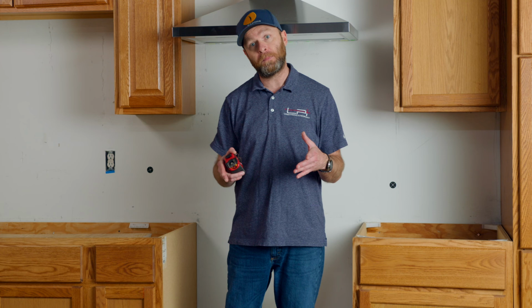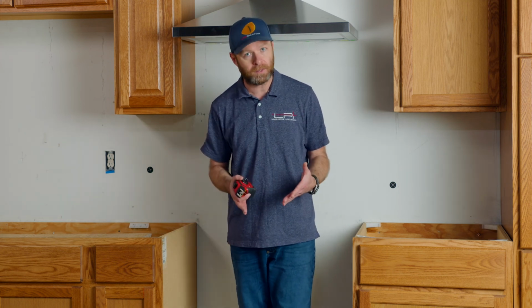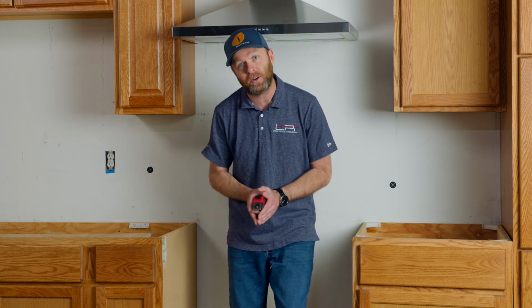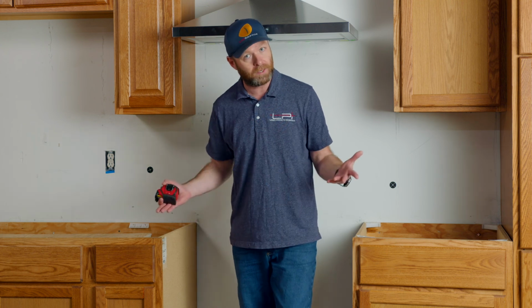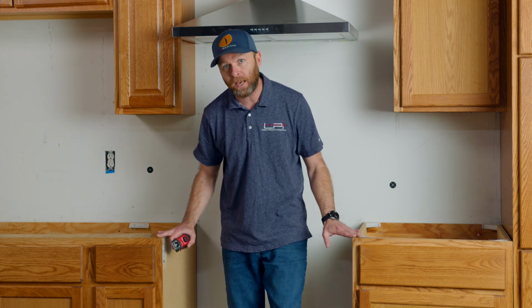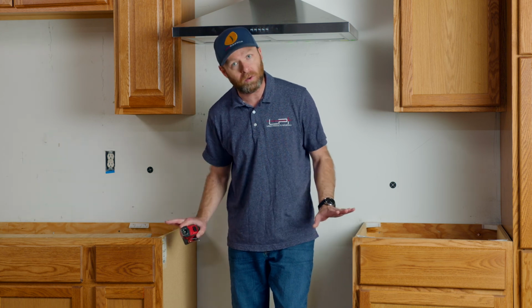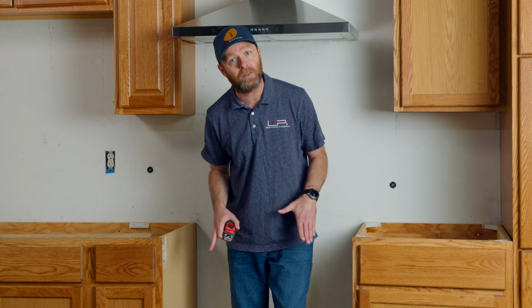When verifying our dimensions, when we get to the stove opening here, one thing we want to take into consideration is that we made this stove opening based off of the center of this exactly 30 inches wide. Now we all know when we get out on these job sites, sometimes these cabinets are set at 30 1/4, 30 1/2. Really don't know what we're going to get. In my situation here, my opening set at 30 3/4.